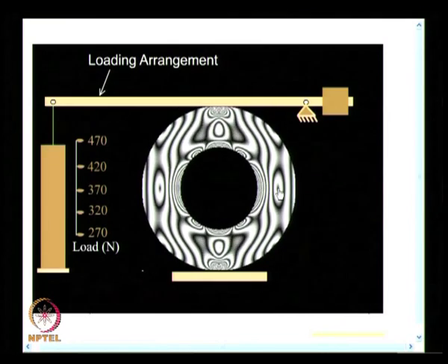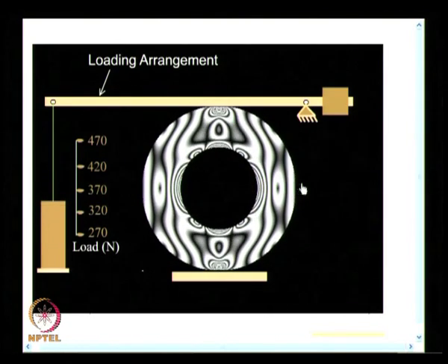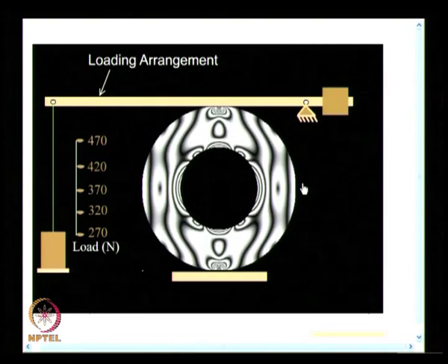If I take a color image of the fringe pattern using white light as a source, then a black spot in a circular polariscope will definitely say it is the zeroth fringe order. If you have a white light source and can look at it, it is well and good. But if you do not have one, you should also have methodologies to identify the zeroth fringe order. But in this case, even if I know the zeroth fringe order, if I do not know how the gradient is along this direction, there is no way I can label the fringes.